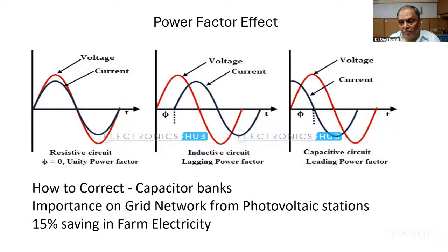At each pump motor, for example, when you're using a motor for a pump, you put a capacitor bank that will hold the current for a very short time, so that it stores the current for a little bit of time. When the current is lagging, it will give the supply. It's like a small storage you keep for the electrons that will supply it. That will improve the efficiency by 15%.